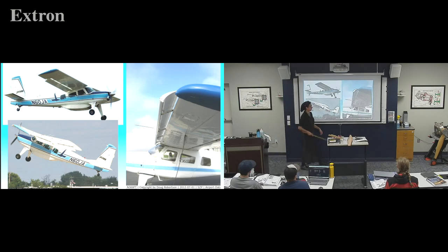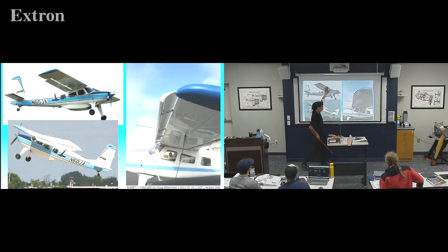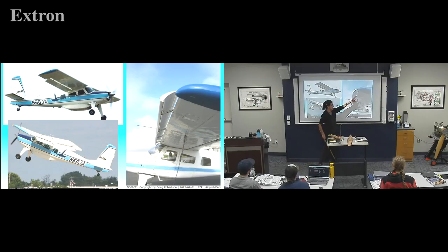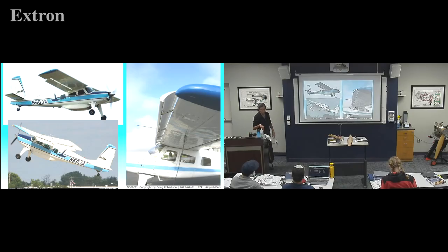are retractable. So they can go in, smooth and streamlined when you're at higher speeds. But then as you slow down on the Helio Courier, they are pushed in just with airspeed. So as you go faster, they push back in. And then as you slow down, they plop out. And the inboard slats will deploy at about 43 knots. The outboard slats at about 39 knots. With the slats deployed, full flaps, stall speed is 24 knots.